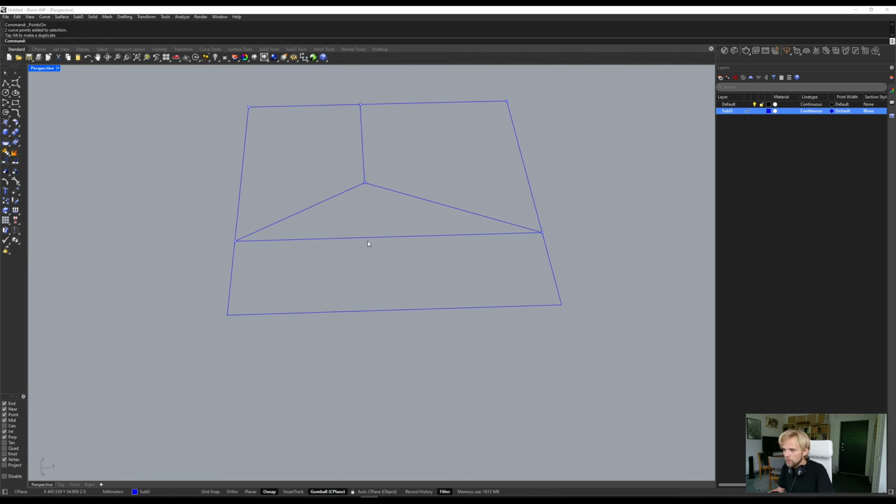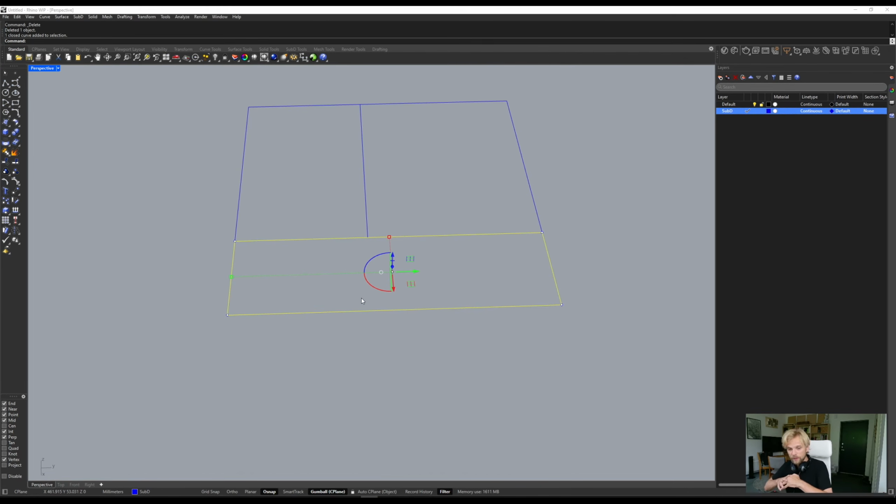So what you want to do in this particular instance is you want your sub-D polygons to always connect corner to corner. You can never have something like this where an edge arrives at another edge, right? Because basically you have points here, right? And every single point of every single polygon needs to connect into this grid, right?